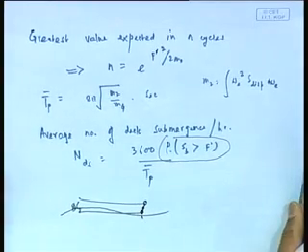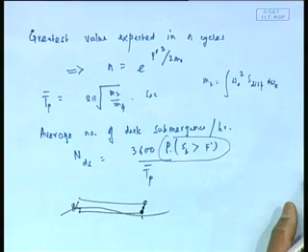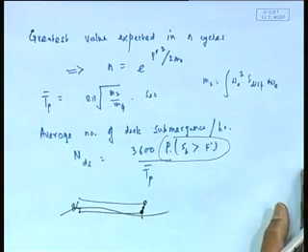Okay. See, all vertically. So, this becomes a very straightforward procedure, and this is exactly what we do. When we do a calculation, in typically a seakeeping calculation, we would first be doing the RAO for the 6 modes of motion, that is the fundamental thing. So, I have the RAO for the 6 modes of motion. Then I will immediately construct all the derived RAOs that I want, like in this case the relative velocity RAO, and then I will find out whatever I want. So, these are very simple.